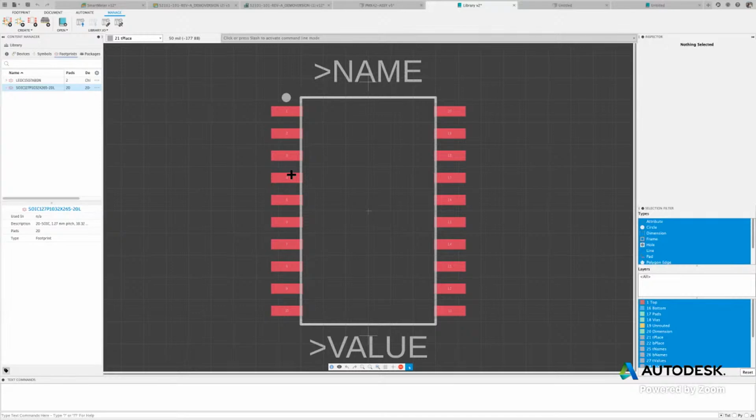For those of you that have been using Eagle, you'll remember that you could place the schematic on the board. As long as they have the same name and the same folder, Eagle will keep track of them. With Fusion 360 being cloud-based, we have created something called the electronic document, which has a lot of advantages, because now I'm able to associate one schematic with different circuit boards if necessary. It's kind of neat. It expands these capabilities. But I'm going to keep it simple today. Let's go ahead and create our first electronic document.